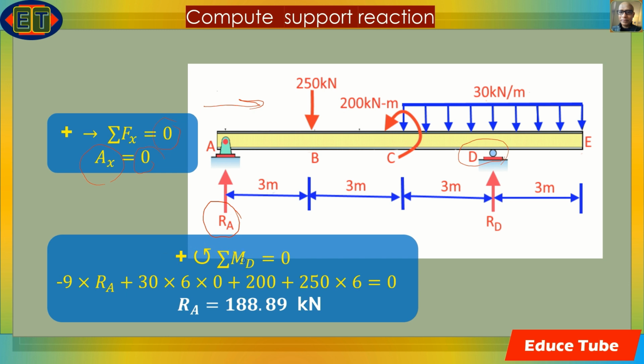So if we take summation of moments at support D equal to 0, we find an equation like: Ra multiplied by minus 9. This is Ra, from here it is 9 meters and it is working clockwise. Anti-clockwise is positive, so clockwise will be negative.